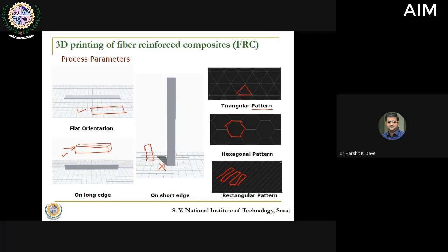This is how they are laid. Now it is interesting to know if you keep 100% density. If you want to make a solid part, then there is no fun in creating this type of design. But when you go for lower density, say 50%, 70%, then if this is the part, and you have decided to have 30%, this is how the part gets deposited.